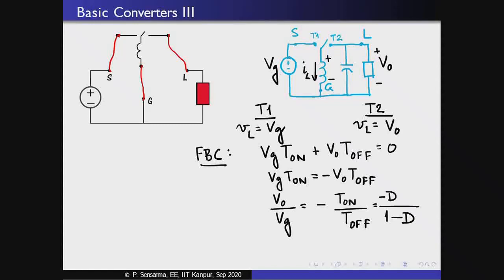Okay. A few things about this converter. Till now we saw that the output voltages for the buck and the boost converter, the actual output voltages were in the same polarity as the reference polarity. But in case of this particular converter, we still do not know what its name or property is, we see that the output voltage that we obtain here, the polarity is reversed. So, now when you actually put, let us say a DC voltmeter, and put the reference point here and the measuring point here, then this voltmeter will give you a negative reading.